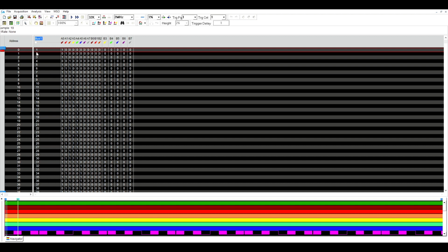So what we are seeing in this column is the video memory address produced by Cavia. If this is working okay, the address will go all the way to 39, and then it will loop back to 0, and then again up to 39, and then loop back to 0, and that will repeat itself 16 times. Then it will count through to 40, to 79, and then go back to 40, to 79, go back to 40, 16 times, and so on. So let's see whether it's doing that.